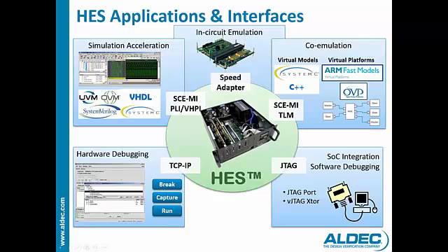We've got in-circuit emulation, or ICE, which connects the emulator to a design with some real device or real peripheral. For example, a real USB device or Ethernet network, or HDMI, to show image data from the emulator.